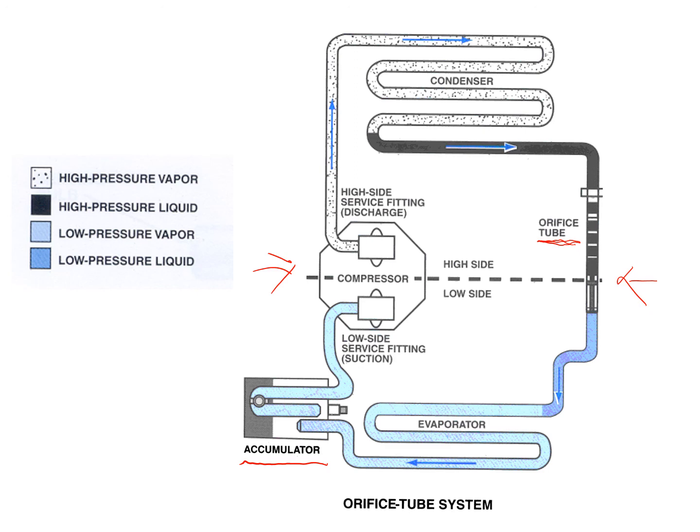As it leaves the compressor, it's going to be all vapor. Same process, it goes through the condenser. The refrigerant is going to give up its heat, condense into a high temperature liquid, and from there it flows to the orifice tube as a liquid. So everything on the high side would be hot. When we get to the orifice tube, the refrigerant is flowing through there as a liquid, and it goes into the evaporator core as a low temperature, low pressure liquid.